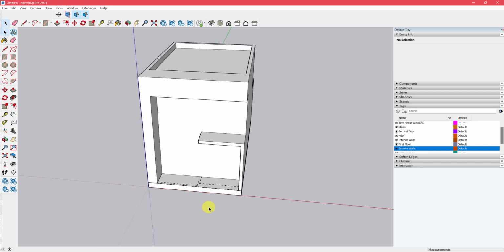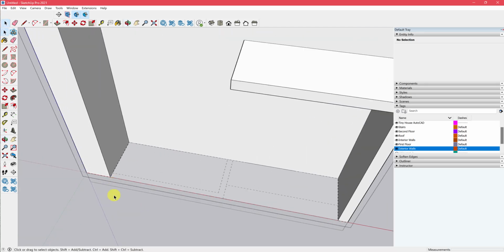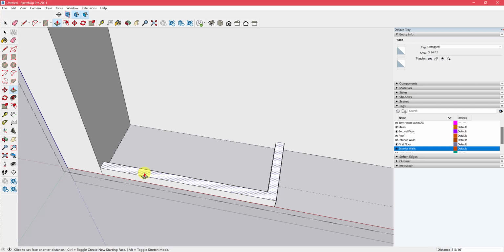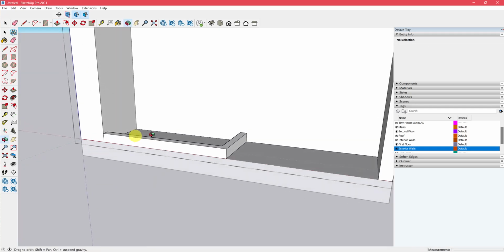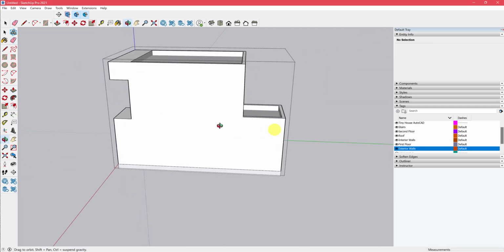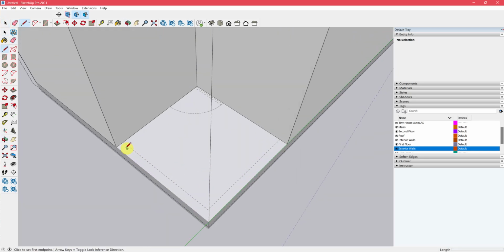Awesome. So we'll go back into our exterior wall group for that. Double click. And I'm just going to trace over those planter walls. Okay, get rid of that middle surface there. We don't want that, just the wall surface. Push-pull that up 6 inches. And erase any extra lines created. Let's orbit around to the back. Do the same thing for these back garden walls. Trace over those lines.